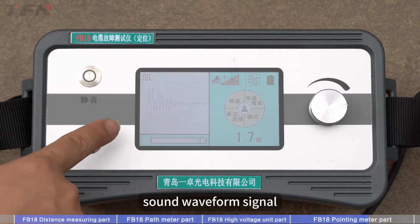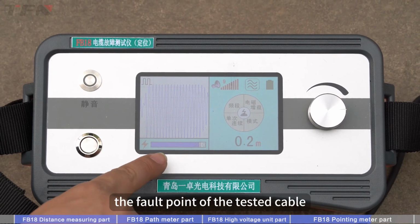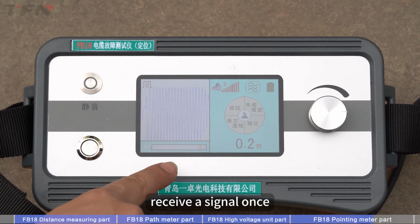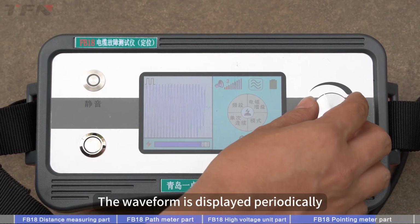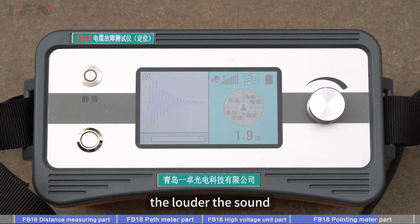Outdoor test. Sound waveform signal and electromagnetic signal will be received just above the fault point of the tested cable. Discharge once. Receive a signal noise. The stronger the electromagnetic signal, the closer to the fault point. The waveform is displayed periodically. The closer to the fault point, the louder the sound.